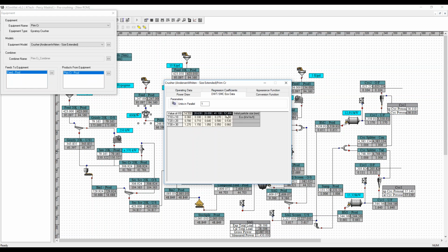These are particle sizes, and these are t10 values, which indicate size reduction. To get more reduction on this particle size, you need to apply this energy level, basically in kilowatt hours per ton.